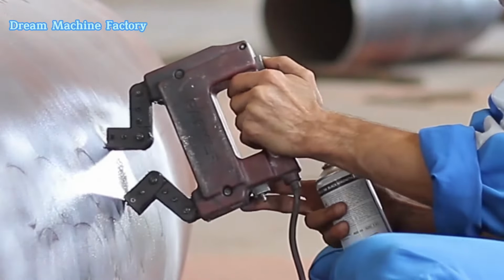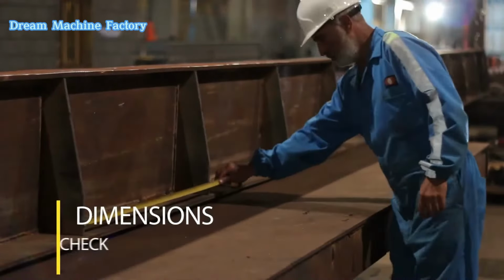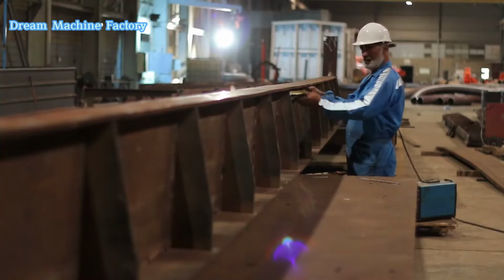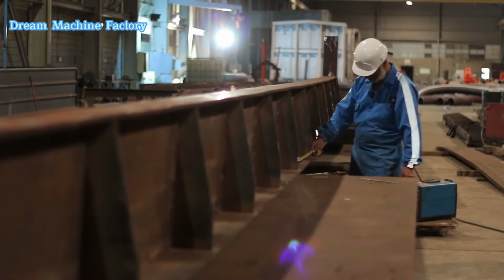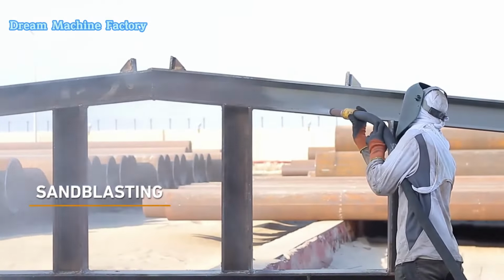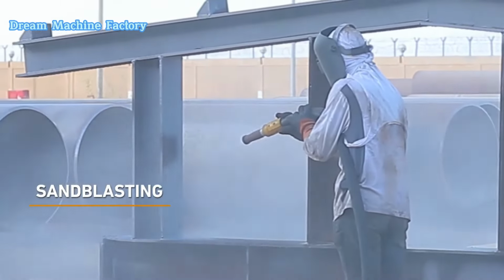After welding and testing, a dimensional check is performed to ensure that the fabricated structure meets the original design specifications. Measuring tools such as calipers, micrometers, and laser measuring devices are used to verify accuracy in dimensions, alignment, and overall geometry. To prepare the steel surface for painting or coating, sandblasting is conducted.